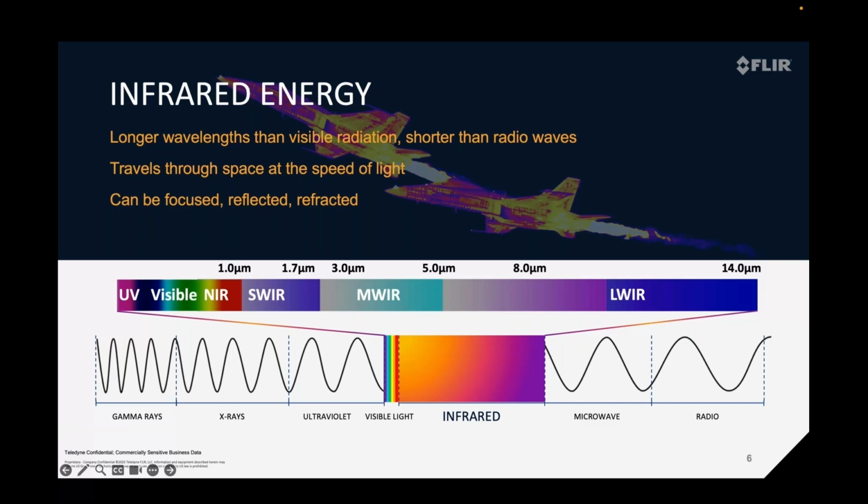Recently, there's also been development in hot midwave options, such as strain layer superlattice materials, which in the past were just long wave options. The slope of Planck's curve here enables excellent contrast. The detectors are exceptionally sensitive at typically better than 20 millikelvin NEDT, and for many applications, there's enough energy to adequately fill detector wells to run very high frame rates in the midwave.